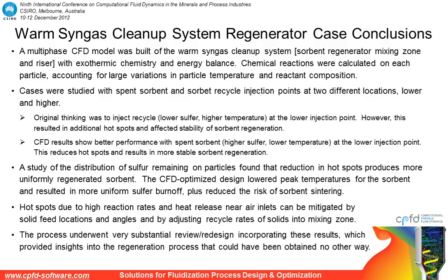In conclusion on the warm syngas cleanup system regenerator case, this was a multi-phase CFD model that was built to model this sorbent regenerator, mixing zone, and riser with the full exothermic chemistry and energy balance. Cases were studied with spent sorbent and sorbent recycle injection points at two different locations, lower and higher. Originally, it was thought to inject the recycle at the lower injection point. However, this resulted in additional hotspots and affected the stability of the sorbent regeneration.